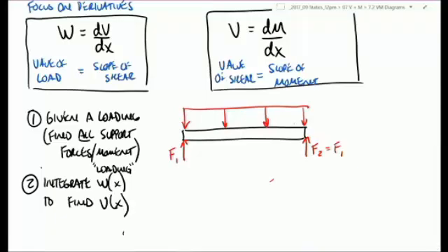Okay, so often we'll draw these shear and moment diagrams right below their free body diagram, just so that we spatially have things nice and lined up. This is a very simple load on this one. We label our shear diagrams V. All of the units in both the force diagram and also the shear diagram are just going to be force units, right? So let's just say that this is in newtons, then this is going to be in newtons. Okay, so shear and loading are both in just force units.